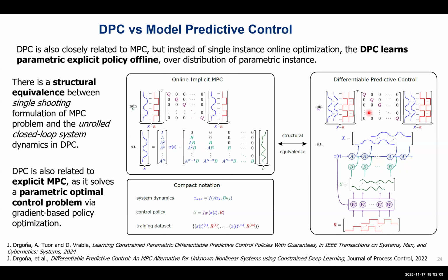In a structural sense, when you look at implicit MPC in its dense form, also called single shooting formulation, in linear system models your state trajectories are uniquely defined by the initial conditions with these matrix powers over here, and this lower triangular matrix, also called dense formulation, that computes the effect of the control trajectories on state trajectories, right? This nice recursion of the state space model.